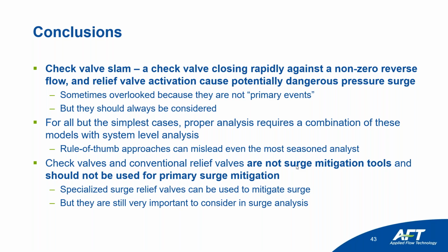It can mitigate downsurge, but usually the surge relief valve needs a little bit of time to reset itself to be able to mitigate both. So it's not a perfect model of it, which is why we had to use the control valve for that case, but they are supposed to be able to handle downsurge as well. But we had, as I said, some slower closing rates than you'd normally see with those types of valves.